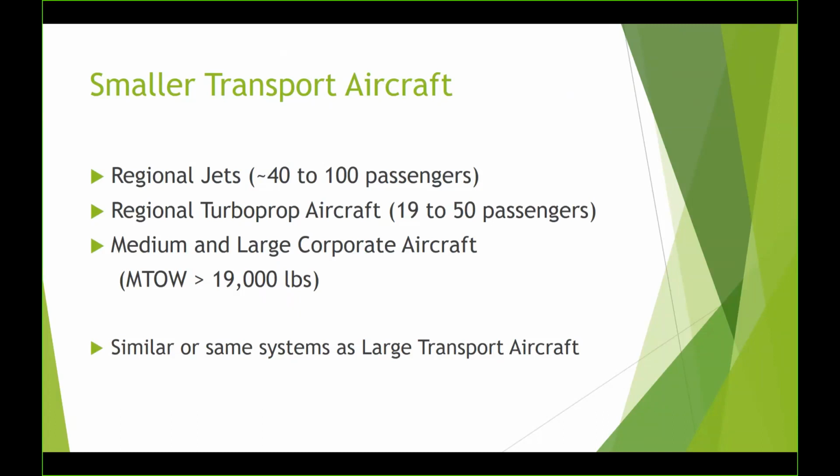Okay. So medium and large corporate aircraft, again, especially the medium corporate aircraft, most of them are not going to have the 19 passengers, but they're going to be over the 19,000 pounds. These have similar, or most of the time, the same systems as large transport aircraft. They might be pared down a little bit, but they're still built under that Part 25 requirement. They still have a lot of the same requirements.